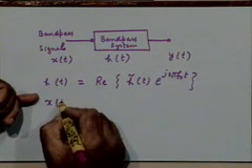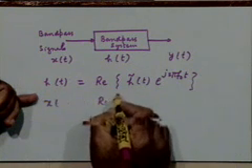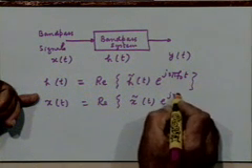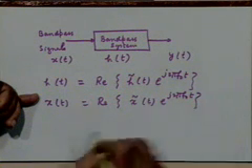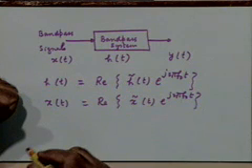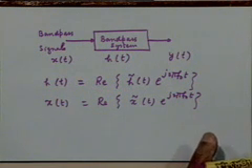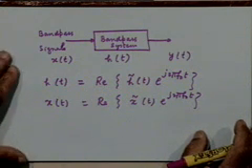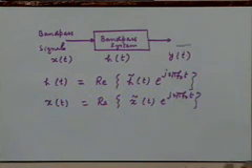Similarly, x of t is the real part of x tilde t e to the power j 2 pi f naught t. Are you with me? Yes, we are keeping f naught the same in both of them, because we are assuming that both the input signal and the bandpass system can be considered to have the same center frequency, right?